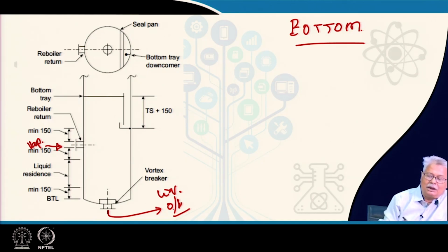Now, you have the bottom tray here, and you will also notice one thing. If I do not have any seal here, the vapor would simply go this way. So, you require a seal here as well. You definitely have a downcomer apron or downcomer skirt, whatever you may say, and an arrangement. I will just remove this part using the eraser, because it will make it more clear.